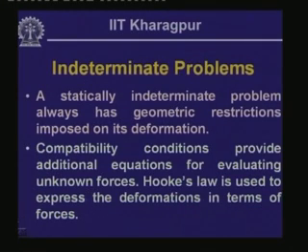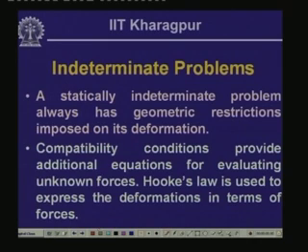So, the indeterminate problems are the ones in which a statically indeterminate problem always has geometric restrictions imposed on its deformation. In fact, from this the compatibility criteria comes in. The indeterminate system always gives rise to geometric restrictions, and these geometric restrictions, when they are expressed mathematically, give rise to the equation of compatibility.